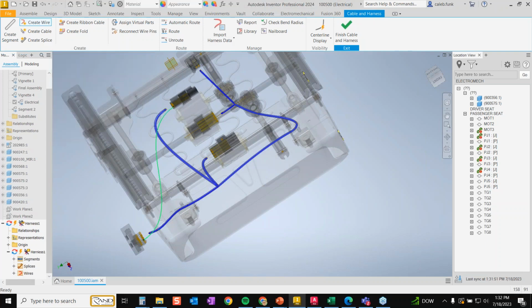And this is what happens when I have a wire, whether I import it or whether I pull it from AutoCAD or whether I put it in just like I did here. When it starts out, it just is sitting in space. It's the shortest connection between the points. It just finds it and goes with that. What I'm going to do is use this automatic route, and I'm going to say just get any unrouted wires and run them through the nearest fitting. And it's automatically going to run it through so that it uses the appropriate information to go through and do that.